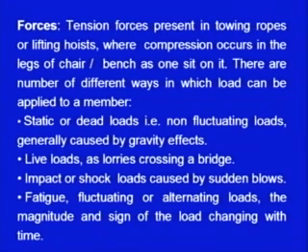So, as we are just watching the bridge, there are a variety of vehicles moving over it. So these are the live loads. These loads can be tensile or compressive, but the magnitude and the direction of the loads are continuously changing with time, as a variety of trucks, buses, and different vehicles are moving on the bridge. So the real loads, we can generally term as the live loads.